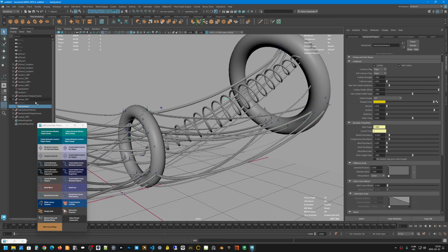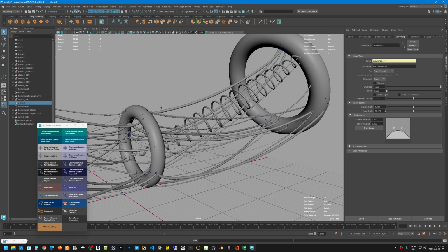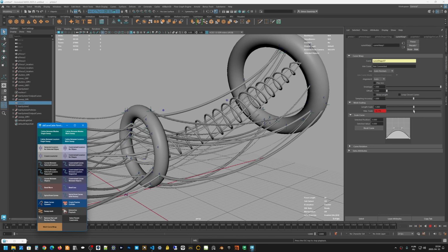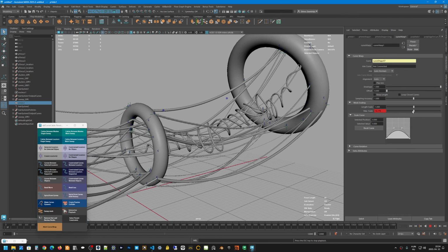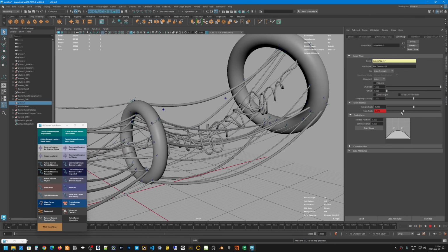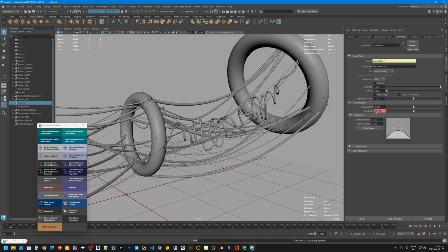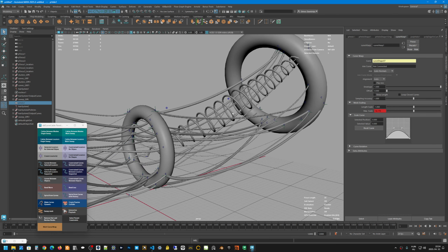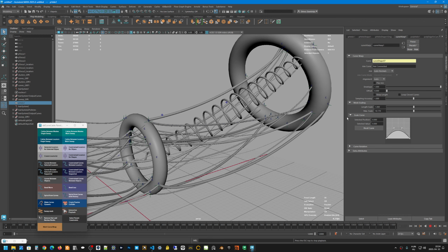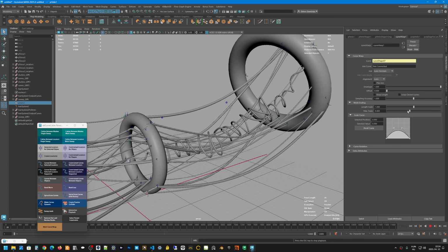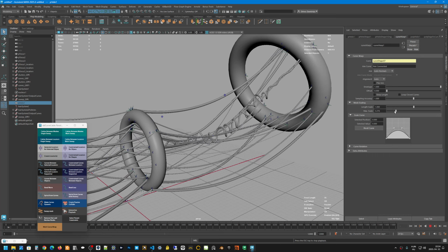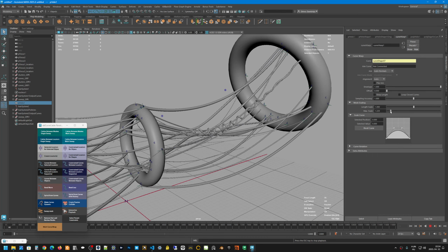But now I can do strange things. Maybe I can animate this max scale value. So if I right click, set key, go to interactive playback, and I start to change basically the radius of this one. Okay, so in this case this will not work. I have to break connection and then play, and then I can adjust this. See, so we started from 10 and now we are back to 1.